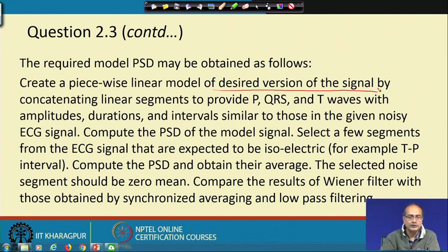If we already know how the signal looks without noise, then the problem is already solved. We would not take the pain to design the filter. As we do not have that, we try to approximate it with a piecewise linear model. In that way we are able to suppress the noise to a good extent, whereas we still keep the overall characteristics of the signal at hand.